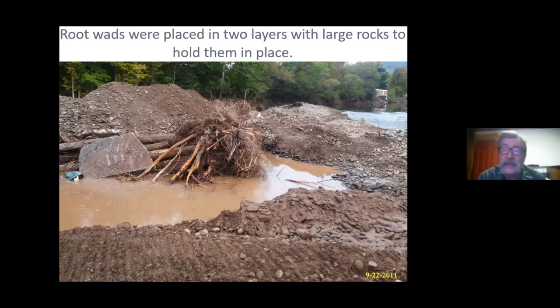You can see here's the main stream over to the top right of our picture. They're working off channel. The avulsion went right through here, near the water supply for that town. And so they're putting in a kind of secondary stabilization or reinforcement in that channel that broke through. They're burying these long stemmed trees. They're anchoring with some rock, and they're going to bury them.